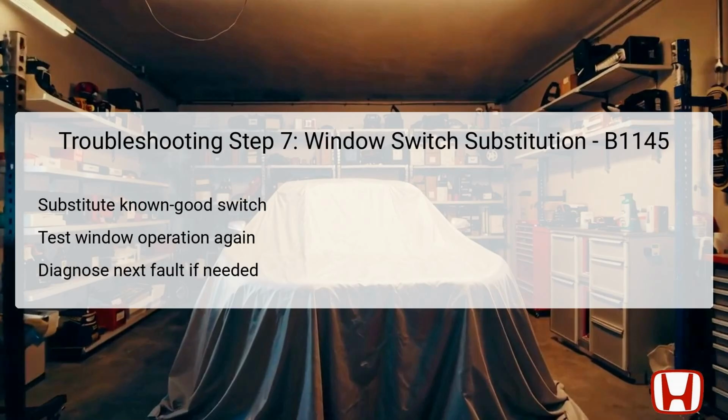The seventh step entails substituting the front passenger's power window switch with a known good unit. This substitution is crucial as it provides a definitive test of whether the original switch was contributing to the problem. By using a switch that is confirmed to be functional, the technician can ascertain whether the fault lies within the switch or another component. After replacing the switch, the technician should again manually operate the window to observe its functionality.